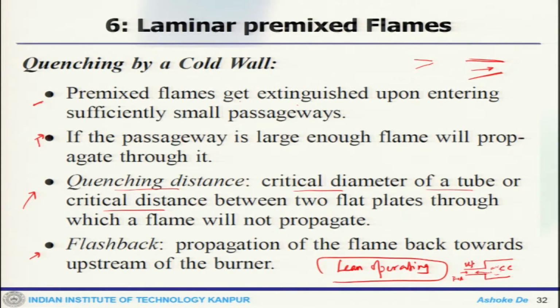This is my upstream block. Now, whether this is a desired phenomenon or not, absolutely not, because if the flame sits on the upstream pipeline or upstream section of this whole system, this can cause severe damage to the upstream injection system and all these things. It is not only detrimental from the structural point of view, it is also not safe, because that can lead to any other accident.